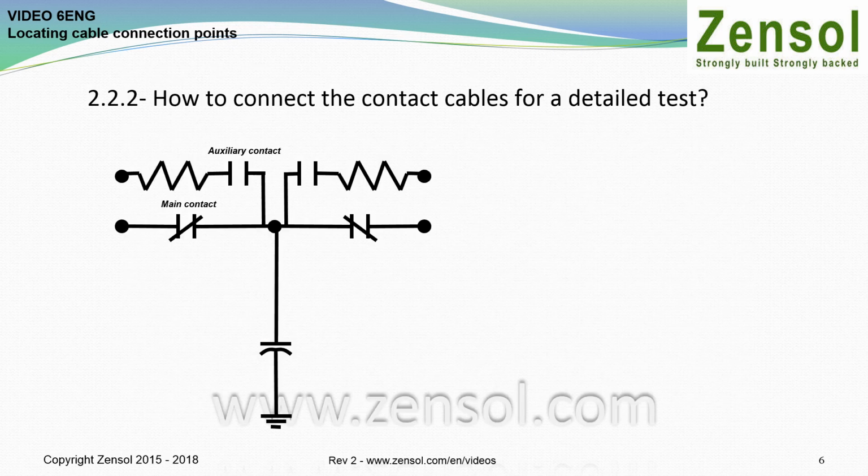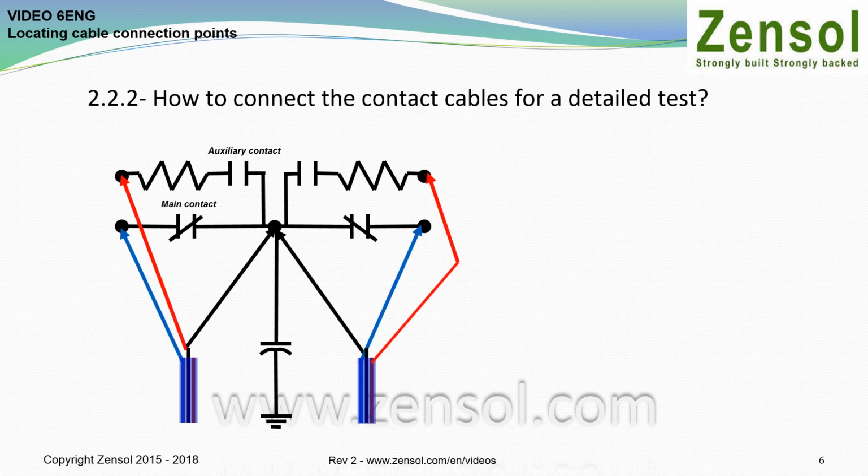How to connect the contact cables for a detailed test. The second method used is the detailed test. Before connecting the cables, it is necessary to electrically separate the auxiliary contact from the main contact. This is done by removing the jumper that connects these two contacts. Cable connections are then made as shown in this slide.